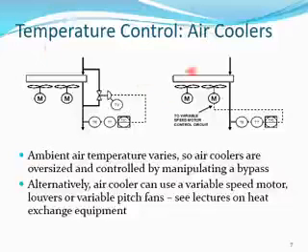Temperature control, for example, air cooler. There is an air cooler. This is the air cooler. You know what's the air cooler? The air cooler is of course cooled by air, meaning it depends on a fan and makes air move between the tubes. There is a bundle of tubes here, and these are fans, which run electrically by a motor to create flow through the tubing, and of course it reduces the temperature of the process flow inside the tube.